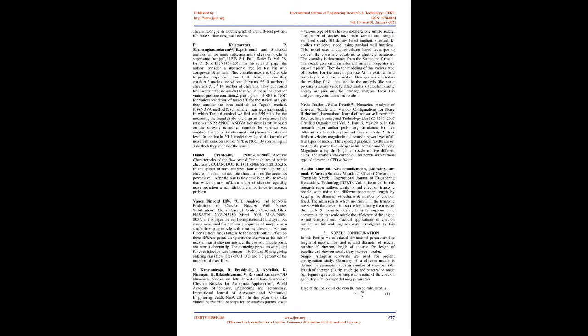Nozzles are used to increase the velocity to get more thrust and also to control the uniform direction of the air-fuel mixture flow coming from the turbine. In the nozzle, the static energy, due to the flow after the turbine, is converted into kinetic energy, and that kinetic energy creates shear between the flow and the surroundings. Because of this, noise is produced in the jet engine. That's why it is necessary to reduce noise from the exhaust of the nozzle.